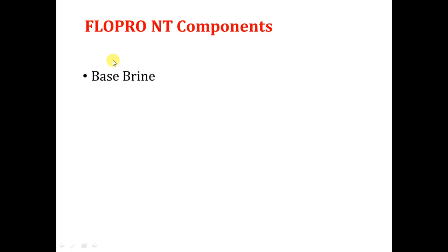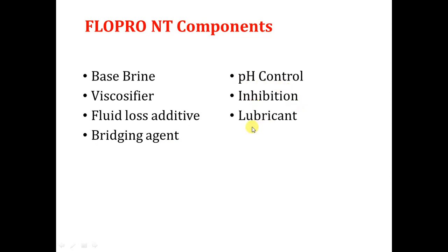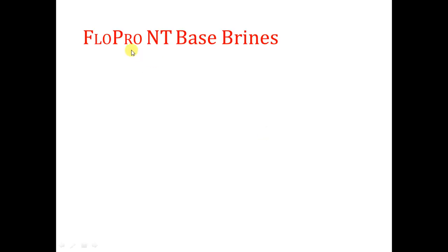Number one is the base brine. Number two, viscosifier, fluid loss additives, and bridging agents, pH control, inhibition, lubricant, and breaker system, in order to damage the filter cake after finishing the job. Okay, so this is very important.